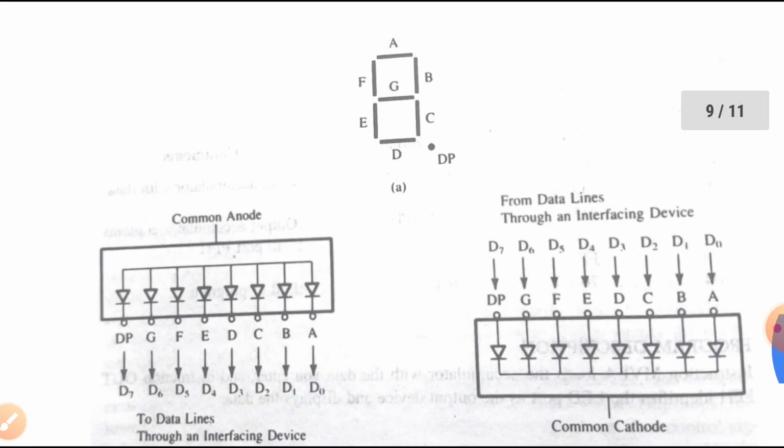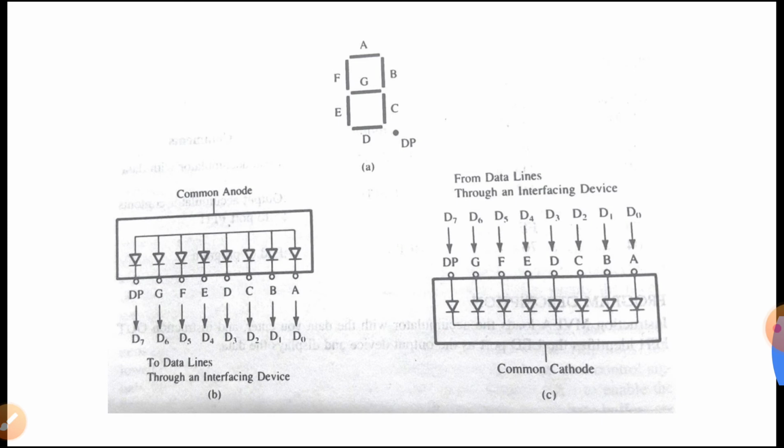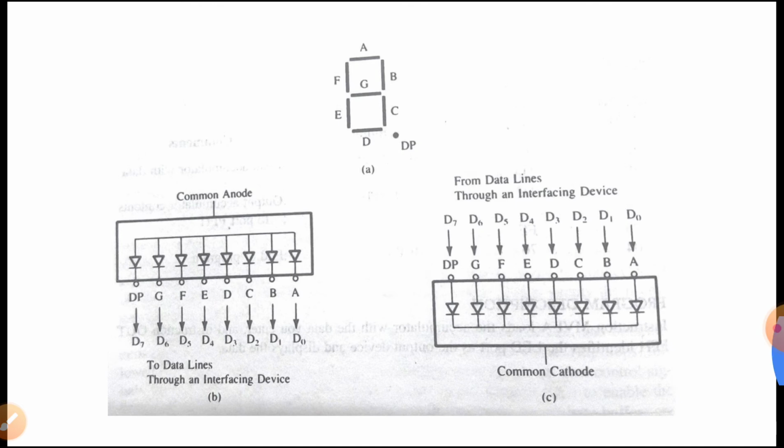Now suppose we have designed a circuit so that we have F5. So we have to design an output port with the address F5. The address lines A7, A6, A5, A4, A3, A2, A1, A0 should have values such that it will be displaying F5.